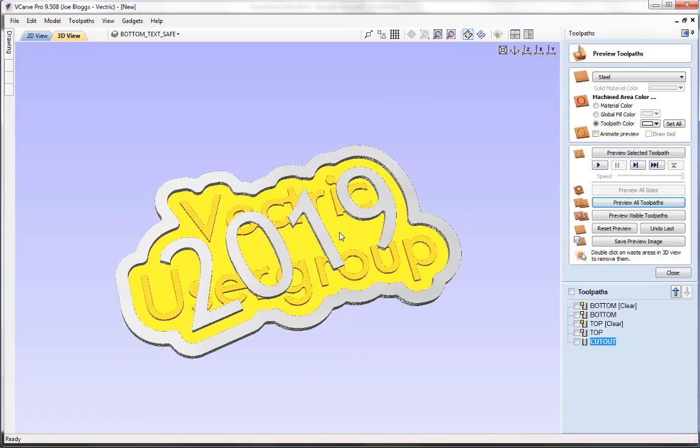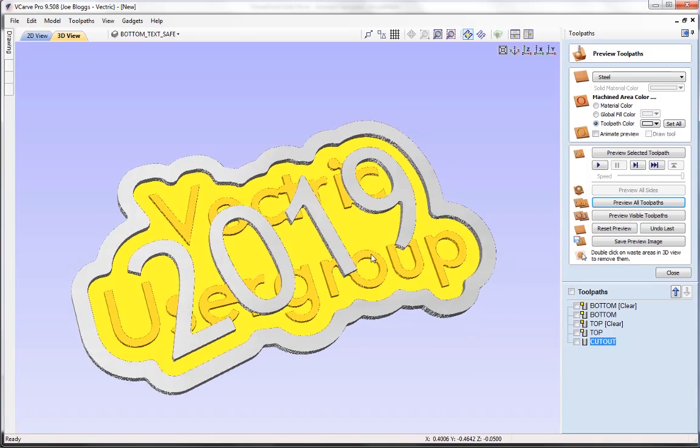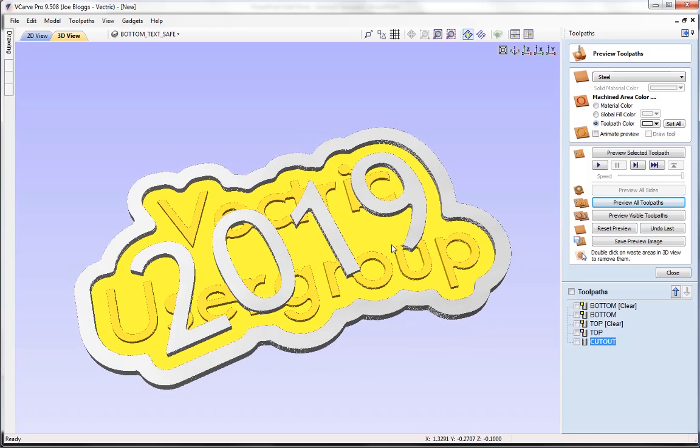And we've created a new badge for 2019. So this was where I took a DXF file with new vectors on, same layer structure, imported that data and simply recalculated all the toolpaths because I'd set up the vector selector to machine any vectors, no matter what they are, on that particular layer using that strategy. So as the vectors changed, all I needed to do was recalculate.